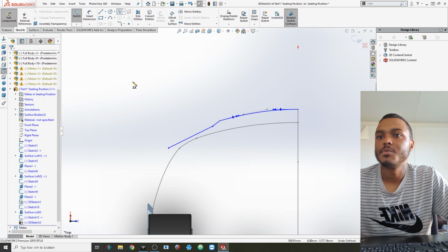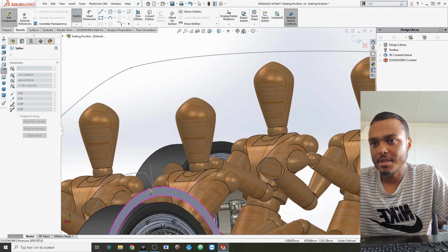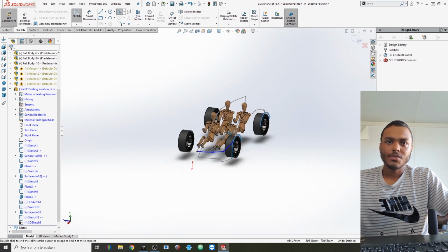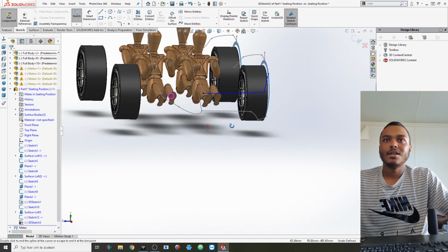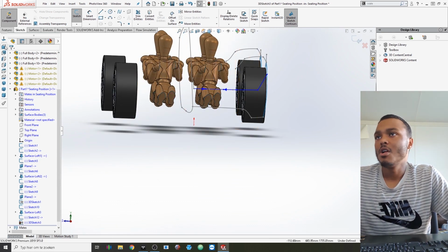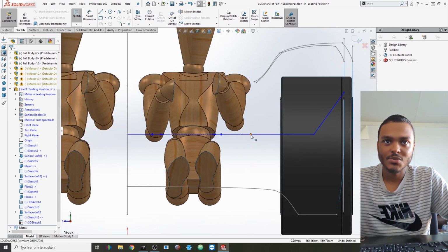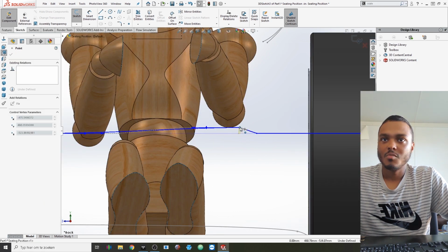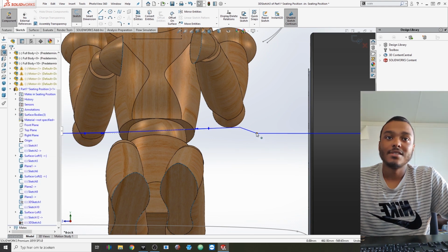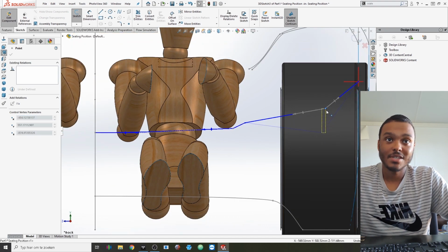And then from this point I can close it off right here, but then I would need to figure out where to land that line specifically. I think somewhere here would do. Here you could already see the thing that I'm trying to do, but I need to make it a little bit more with a curvature to it. This is the rear angle; from the front angle, you can see the separating pieces right here, but I want that line to come up already here, and then have this line do that. So that is basically the whole principle: using 3D sketches and then converting them to surfaces. That is basically everything.